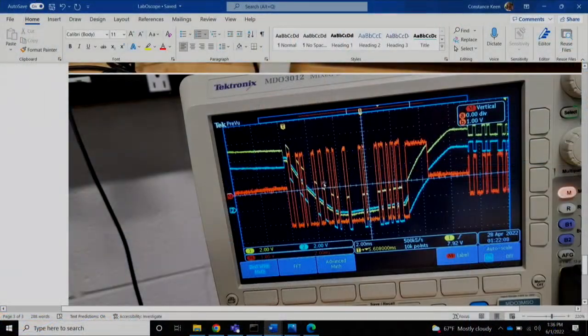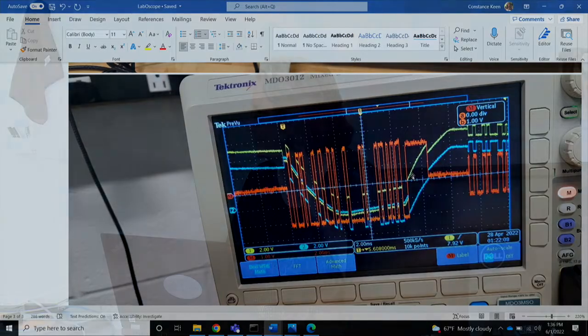And then apply the math function to it. So this looks like, I mean, the scale is screwy and everything, but this looks like what you get when you look on YouTube or something for, oh, this is what your Modbus signal should look like, right? All square and nice. So that's the math of those two, the difference between those two differential signals. And it looks good, right? You would think, oh, this is perfect, but in reality you've got that wave on it, and that demonstrates why you're doing twisted pair and differential signals, right? Because that common noise is now gone.